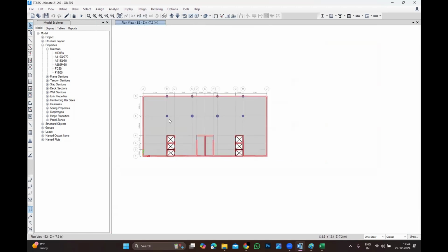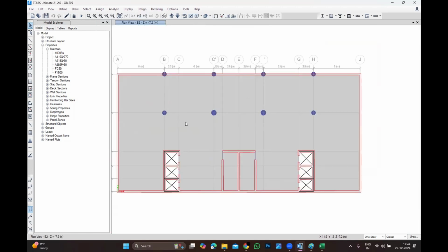Especially precast, you should be more careful. When it is executed, you need to read the drawing, which is load bearing and non-load bearing, whenever they ask for an opening. Even for hollow core slab, people used to do further openings. You can cut 2 strands.